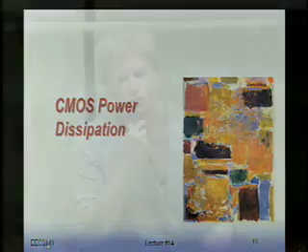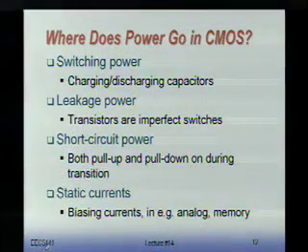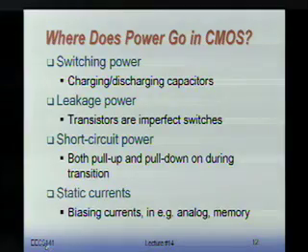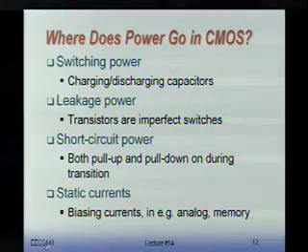If you look at the CMOS inverter, we have given you so far this equation, right? The power dissipation you're going to consume is CV squared. If I flip an inverter around, CV squared goes on my supply, and CV squared over 2 gets dissipated in the first part of the action, and CV squared over 2 gets dissipated in the second transition before we're back. So we have a full transition from low to high to low. We consume basically CV squared.